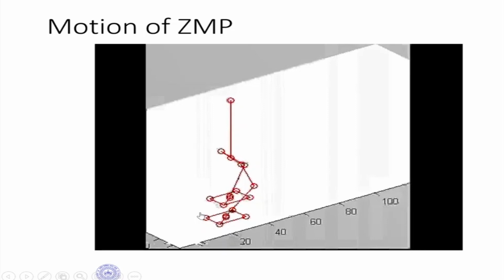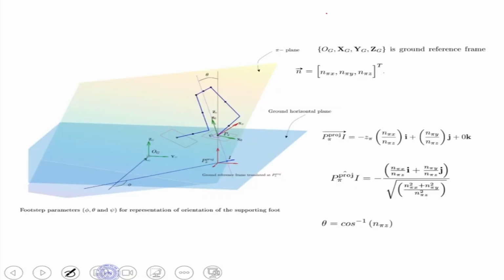Okay, let us just move forward. So we are here, and we said that when a biped robot walks on flat ground, then there are infinite trajectories which are possible. So there is a leg trajectory and there is a hip trajectory. And in the last class, we looked at how to optimize the leg trajectory and the hip trajectory and minimize the torque, where energy is equal to tau into d theta dt. So this is the total energy that is being consumed, and based on that, we find the leg trajectory which is best.